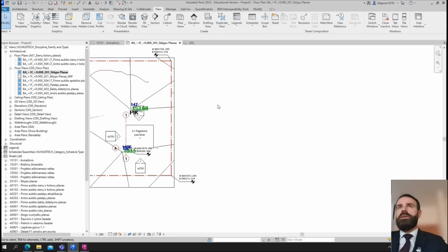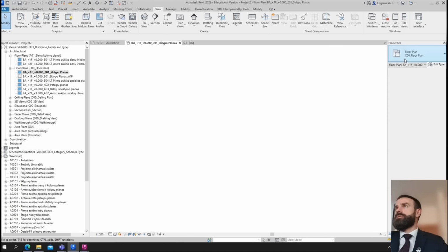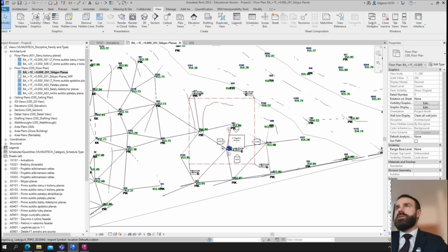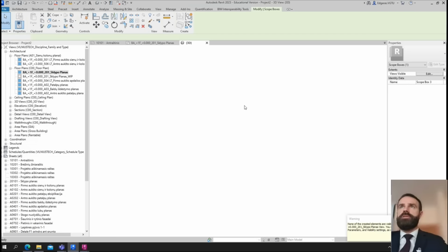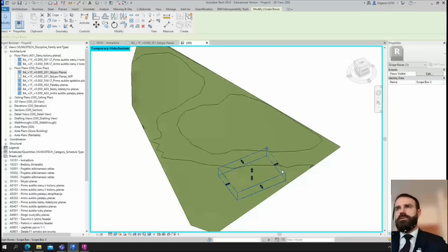And in site plan view, if I go to site plan view, browse, user interface, turn on properties, turn off cropping, and in here I can create scope boxes on my buildings, and these scope boxes will represent location in which my buildings will be located.